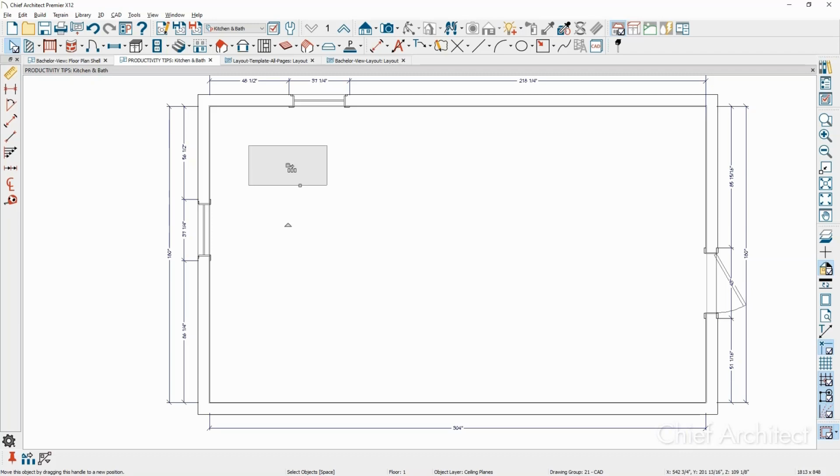I hold my right mouse button down and I click to the right until I feel like it's enough of those objects. I then totally release the mouse. I'm not touching it at all. I pull it down, again not touching any of the clicking buttons, and then left click. I call it the right click, left click.